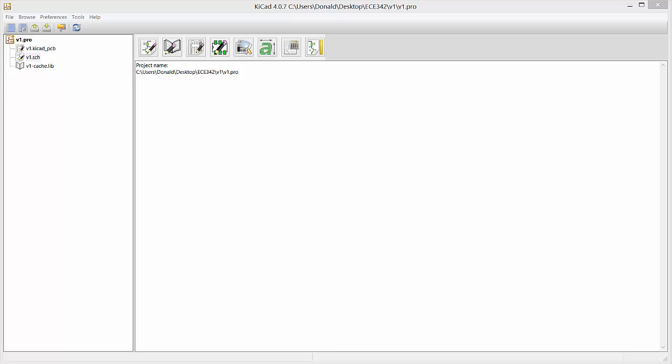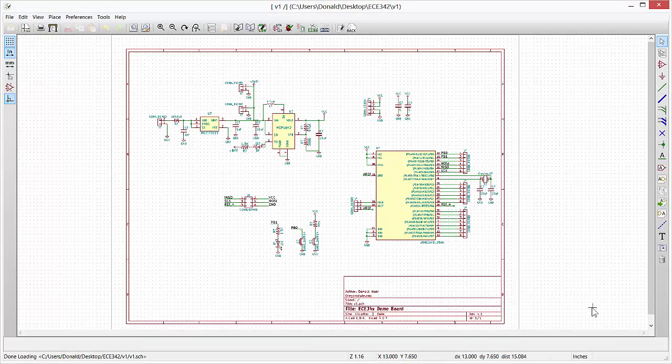To refresh your memory, here's the schematic that we're going to implement on our PCB. As a reminder, it's a lithium polymer battery charger with a lithium polymer battery, here in the middle where my cursor's at, and then that goes into a boost converter which will produce 5 volts on the output. That 5 volts is used to power a Mega 48 chip, which can be reprogrammed using AVR ISP, as well as a couple buttons, one for reset, one for just user, and then a user controllable light. Additionally, there's multiple connectors that are available so that you can connect these two different pieces of hardware.